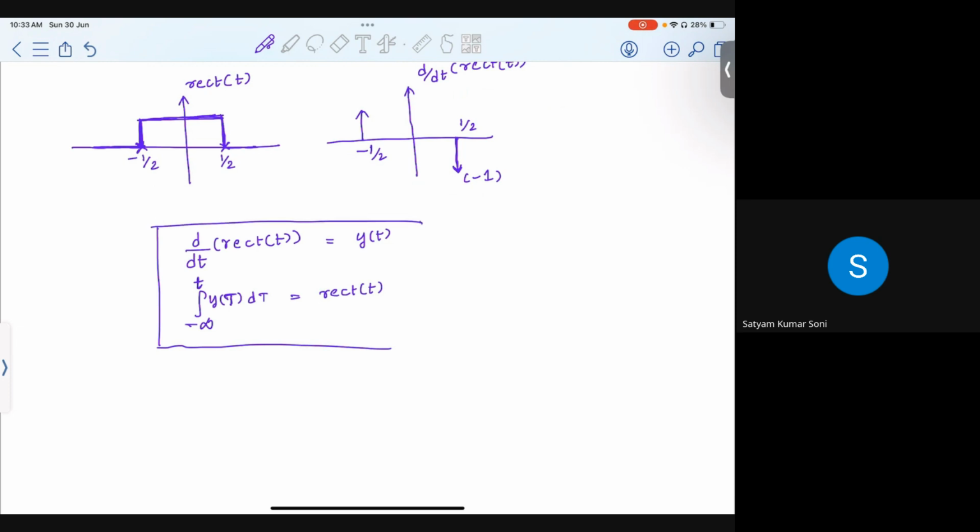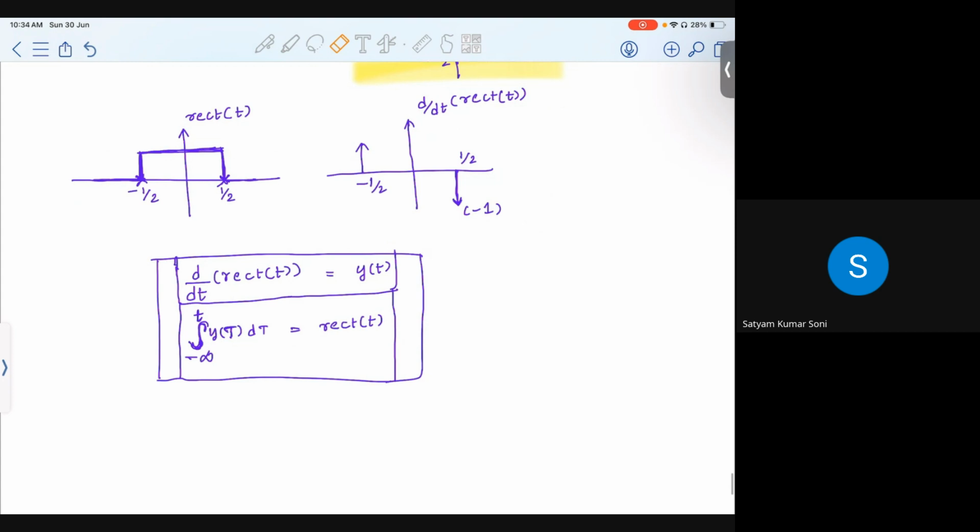For this particular signal, doing it one way will not be sufficient because there are some edge points. So when you integrate your differentiation, integrating a 0 will give you 0, which is not giving you the original rectangular function back, right? When you differentiate the function and integrate that output, it should give you back this function.